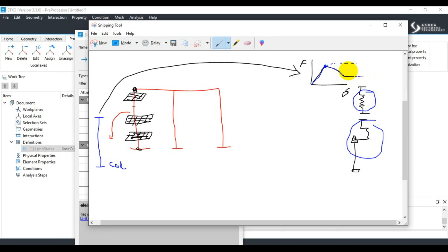Given such a definition for the parameters in a model, researchers can evaluate the influence of column shear and axial load failures on the response of building frame systems. This lecture will describe how drift capacity models for shear and axial failure can be incorporated in an analytical model to detect and initiate the specific strength degradation of those column elements.